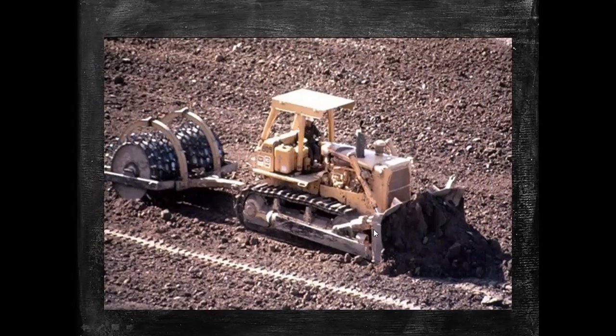And the leveling of the soil can also be observed here. If there are any undulating surfaces, this crane bucket can help with leveling the soil. And this sheep foot roller can compact the soil so that no damage occurs, and it also increases the stability of the soil, and erosion damage can be reduced by using this type of compaction.